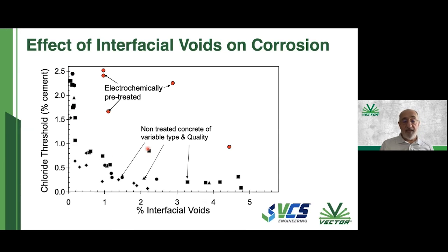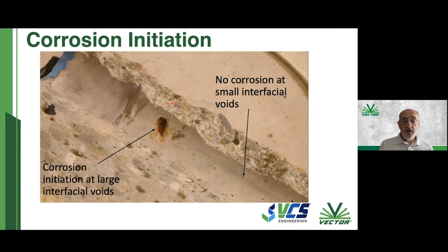But they also achieved the same thing by using ordinary concrete, which is that sort of range over here, and electrochemically treating it, i.e. passing a cathodic current to the steel for some months. And they were able to tolerate, again, much higher chloride contents. And they noticed that there was a layer of alkali being produced on the surface of the steel. And this is what they found, really.